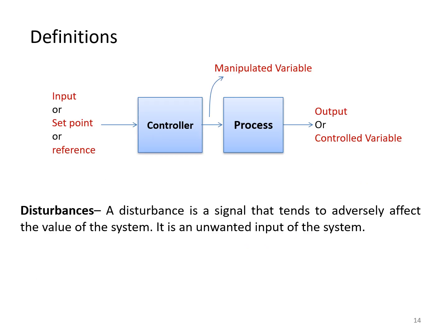Now coming to the definition of a control system, this is the basic block diagram representation of a control system, which incorporates a controller along with the process. Here the input could be a reference input or a set point which is given to the controller. The controller will generate the manipulated variable that is required to perform an operation for the process, and the process will do the operation on the given variable and generate the necessary controlled output value. Okay, so this is the basic block diagram of a control system.